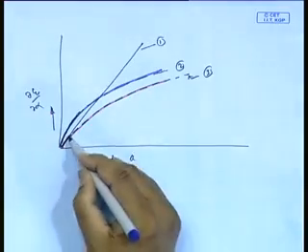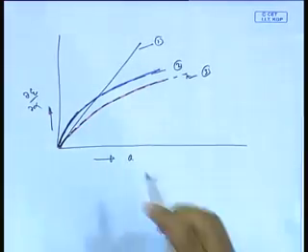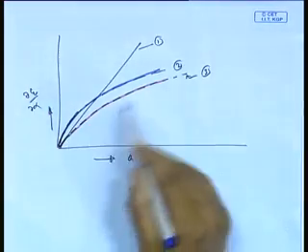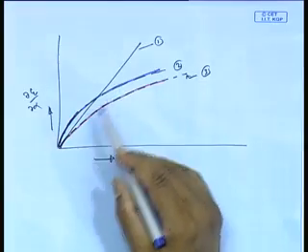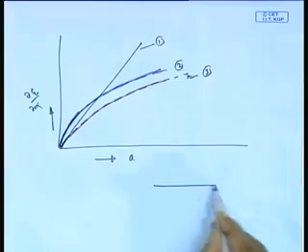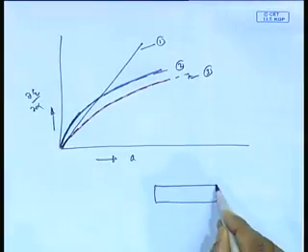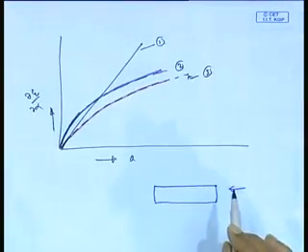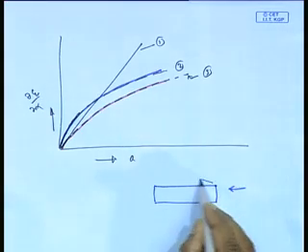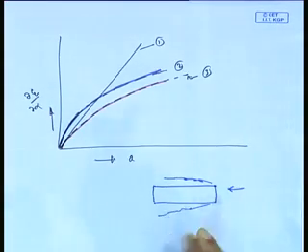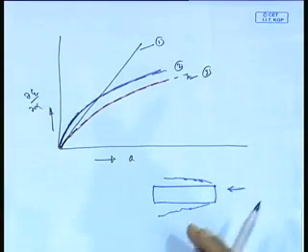There is a reason for my telling that, because it tells me that you should not actually have a very low aspect ratio. It's not good. What is the physical reason behind that? Suppose you take a rudder like that, flow comes this way. What happens? Water actually may separate out. There is a much more three-dimensional effect.